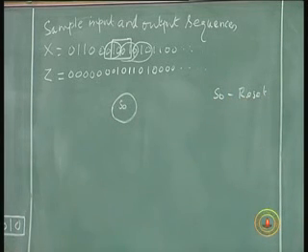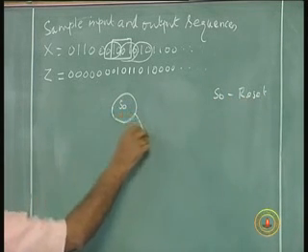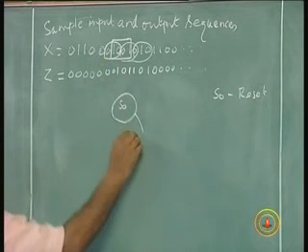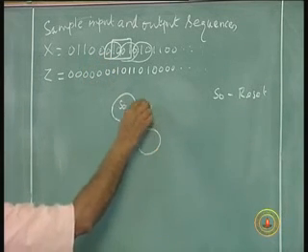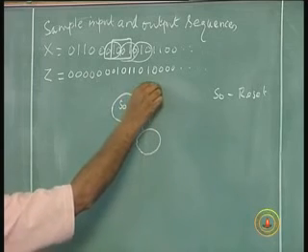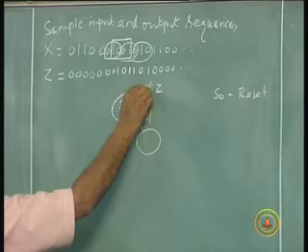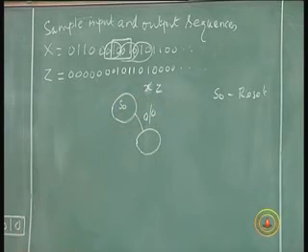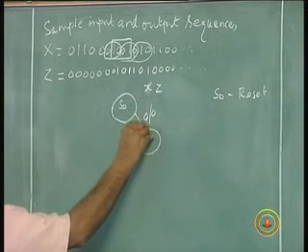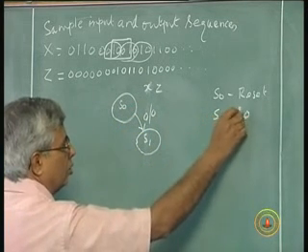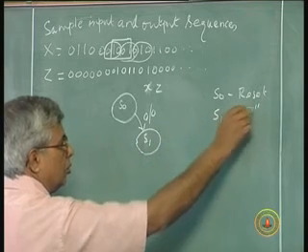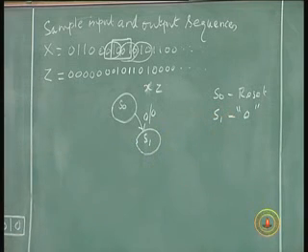The input is a 0. It could be the first form. If an input is 0, output is 0, so x and z. Output is 0. Go to state S1. So S1 is a state where pattern 0 has been identified.